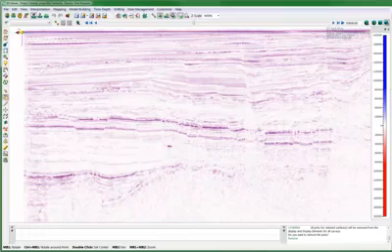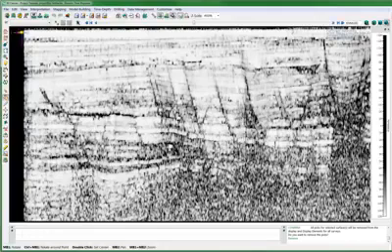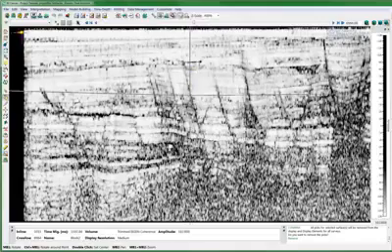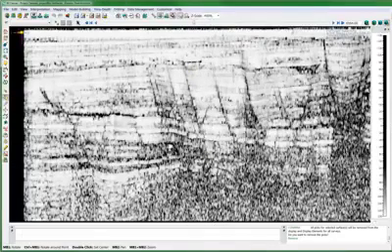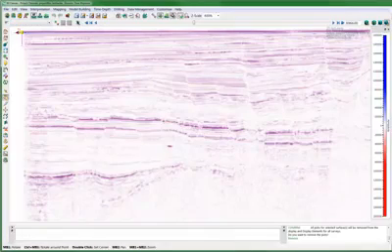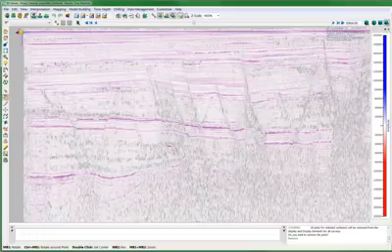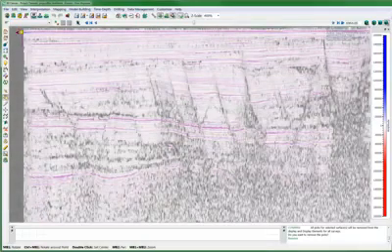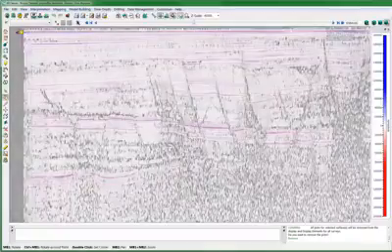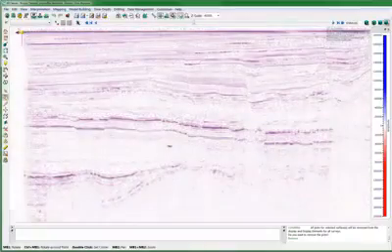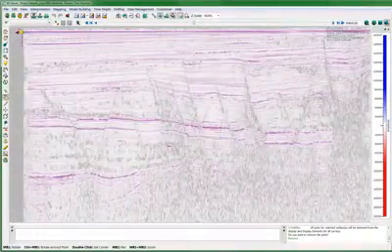The idea is to start picking on the amplitude, but we want to use some seismic attributes to help with the fault picking. For example, we can display coherency. However, picking on amplitude or coherency alone might induce some fault location errors. What we want is to display both attributes at the same time. By playing on the weight of one attribute versus the other, I will be able to give more importance to amplitude or coherency.